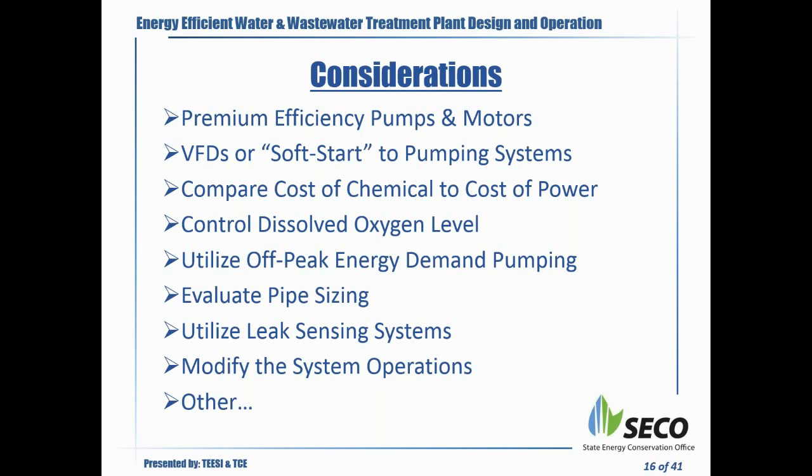And then we also look at modifying the system operations, basically. So we might be asking questions about what kind of operations you have, and there might be an opportunity to improve that. To give you a quick example of that, not a specific example, but recently we were looking at a facility where we realized that the operator was actually doing much more than what the permitting requirements were, and according to him, he was trying to do a much better job at it, but when we did the calculation of how much energy was being used to do that extra, it became evident that that is something, the practice, that they shouldn't be doing.